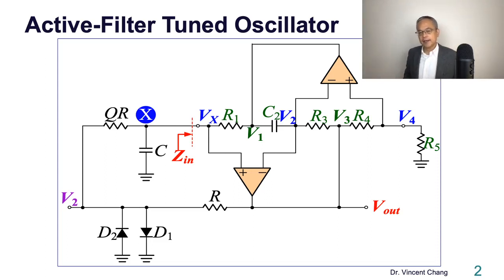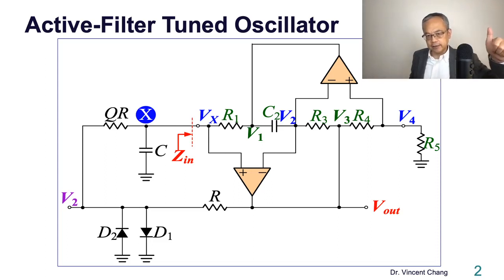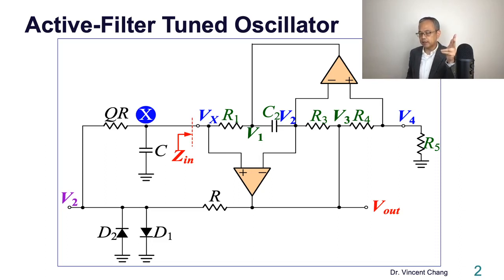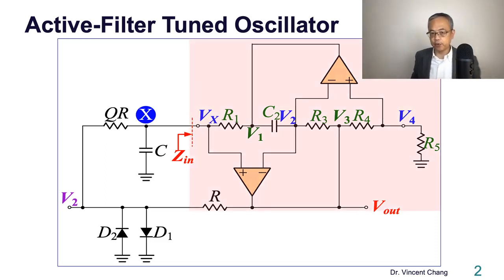Okay. The first is the general impedance converter, an Antoniou inductance simulation, and then it's embedded with a bandpass filter, and then the clamping circuits. So three parts. Let's start with the Antoniou inductance simulation. And this circuit, the red highlight, is going to simulate an inductance.